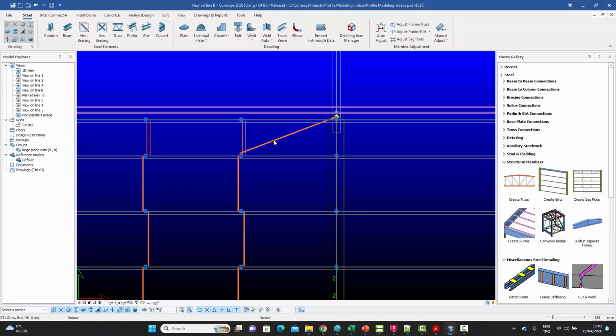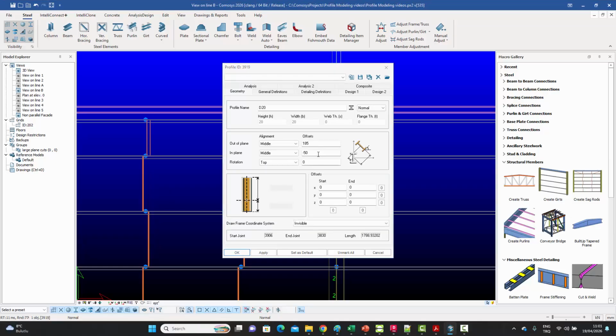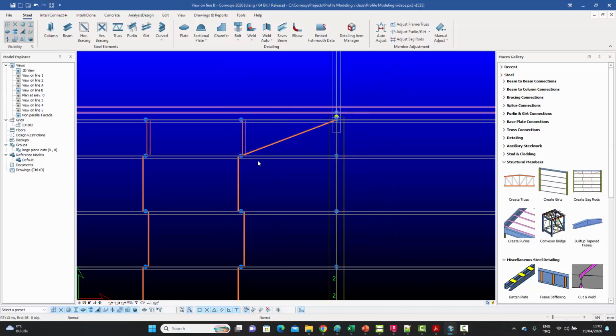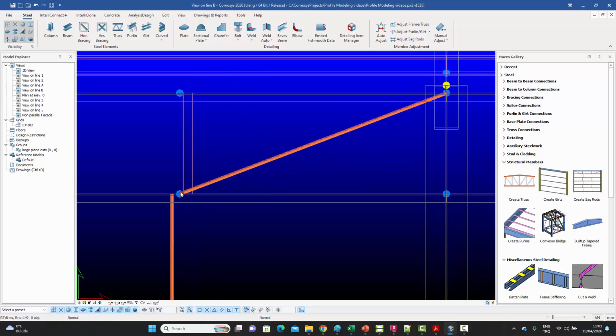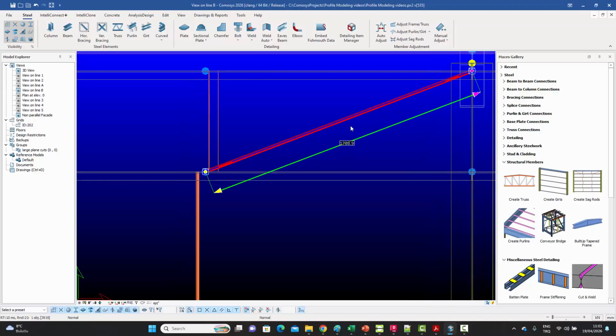But with one exception, you just first double click and you remove this offset of 50, so that it's exactly at that definition point. And now we need to shift it 200 millimeters to the right over here and 200 millimeters to the left over there. And to do that, we know the easiest way is to use these handles.